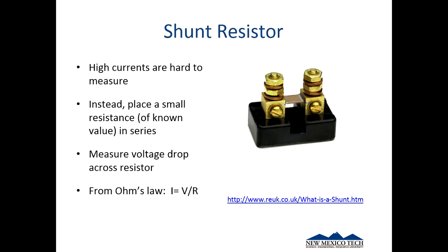If you think about how you had to measure current, where you had to break open the circuit and put your meter in place and hope for the best, open this so that your meter is part of the loop, that can be a little bit dangerous. In general, you don't like opening up connections that are going to have high current through them, because just the littlest bit of dust or anything like that is adding resistance to your circuit. And so maybe you don't tighten it back down all the way or something like that. It's a real nuisance to measure current on high current applications.